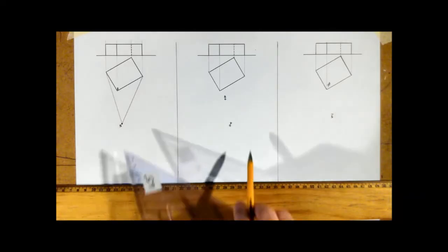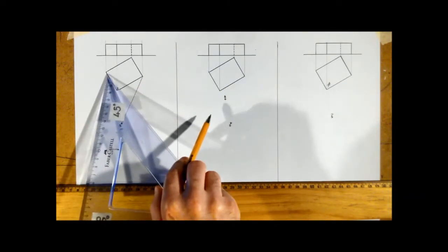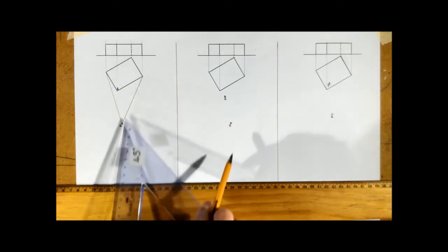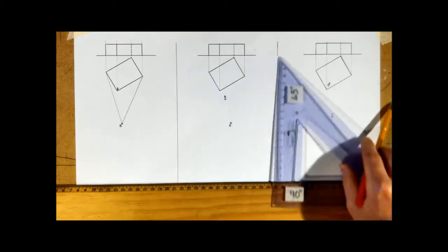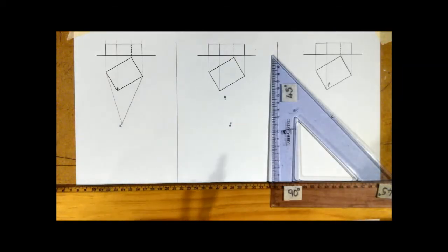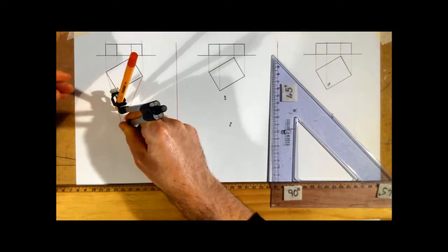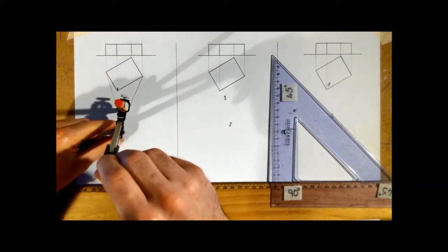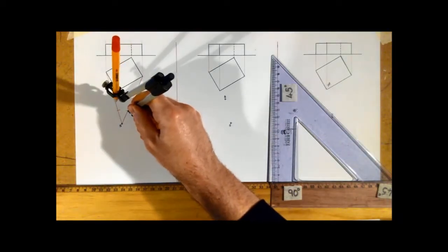Now, what we have to get inside that cone of vision, because obviously we don't know what is in their peripheral vision going off to the left and off to the right, is this: there's an angle inside here, and we have to bisect that angle that was created by the cone of vision. When we bisect it, we get something known as the line of sight, because that line of sight is directly in the middle of the cone of vision.